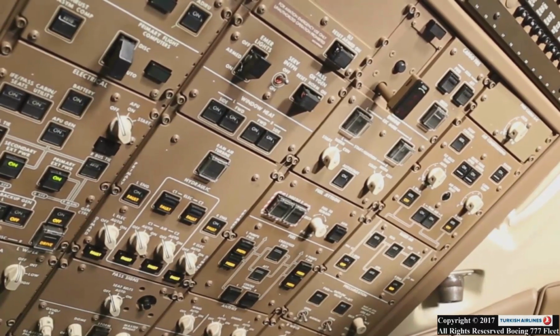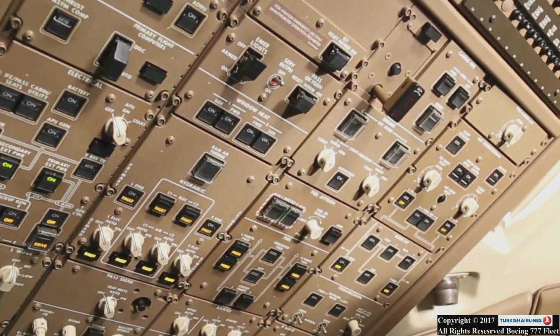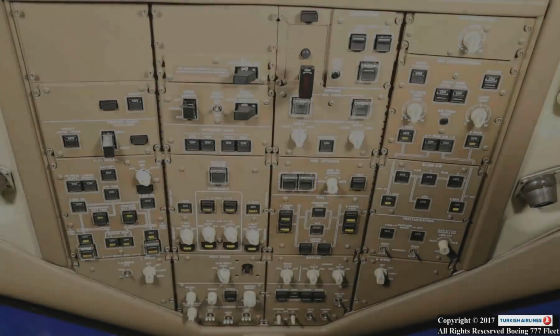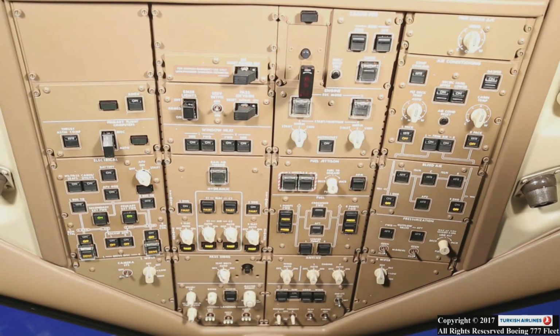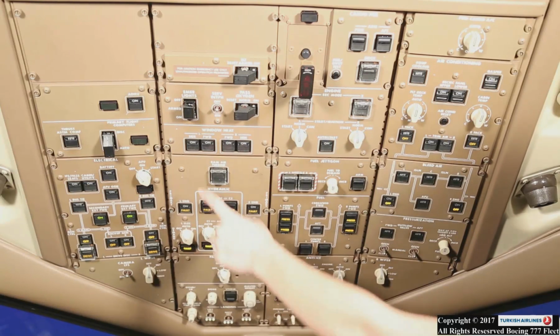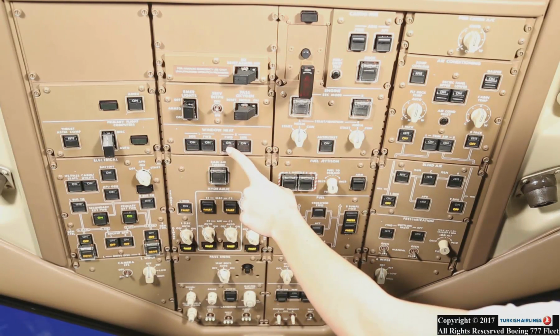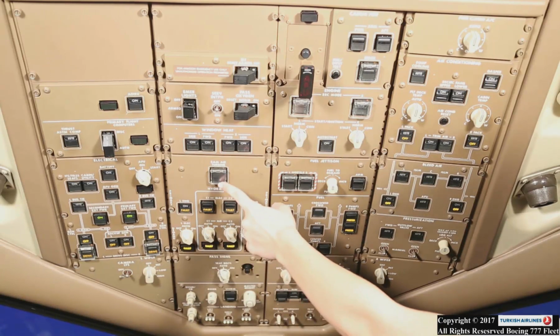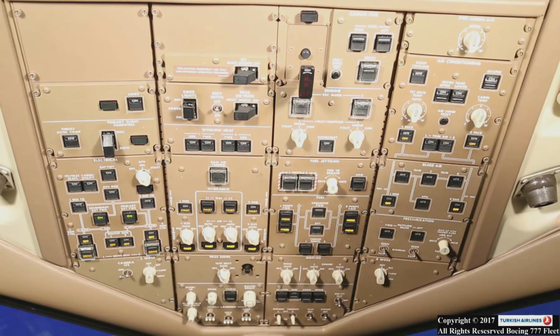Don't push the passenger oxygen switch. The switch causes the deployment of the passenger oxygen masks. Passenger oxygen on light, verify extinguished. Window heat switches on. Verify the inoperative lights are extinguished. Warning: don't push the ram air turbine switch. The switch causes the deployment of the ram air turbine. Ram air turbine unlock light, verify extinguished.